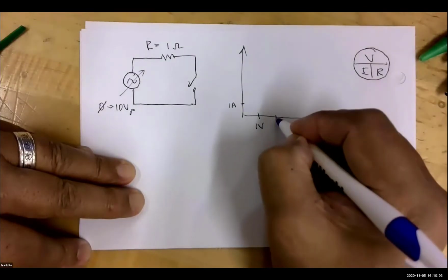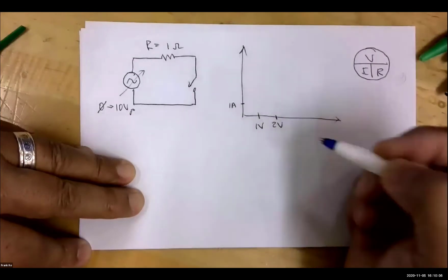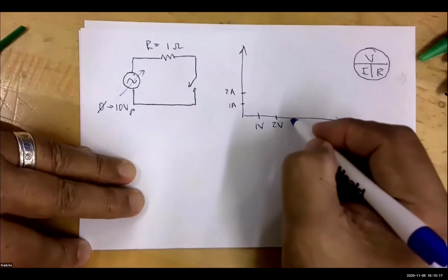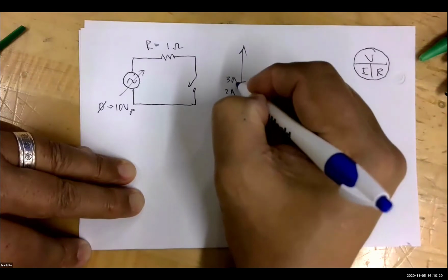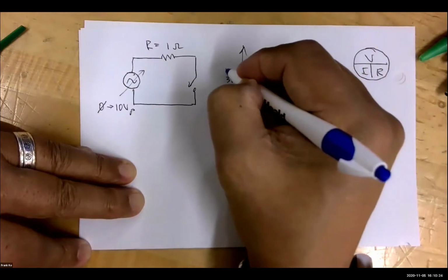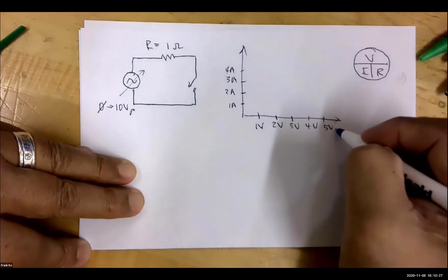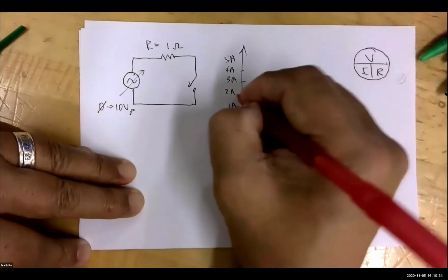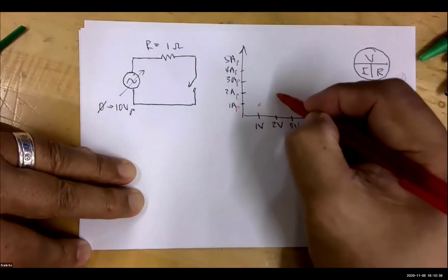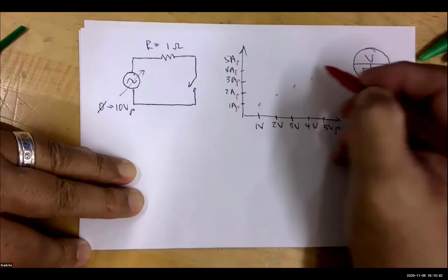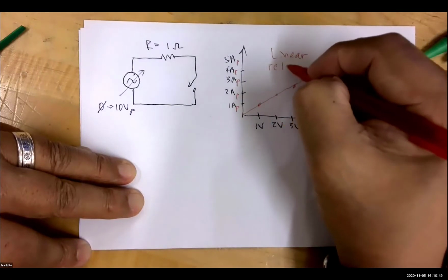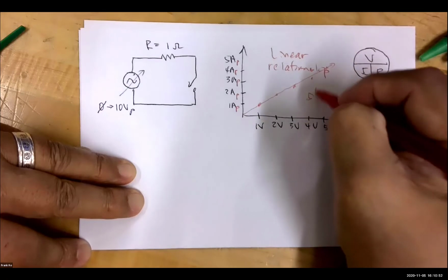Suppose I double my voltage. Suppose I go to 2 volts, but my ohms stay here. What is 2 volts over 1 ohm, Brad? That's 2 amps, precisely. So if we continue with this, 3 volts will give us 3 amps, and then 4 volts would give us 4 amps, and I go to 5 volts peak, these are all volts peak, this will give us 5 amps, and yes, these are all peak as well. Let's start off with peak voltages. So if I go to plot this like so, I have, again, what type of relationship? I have a linear relationship. And linear means straight line.